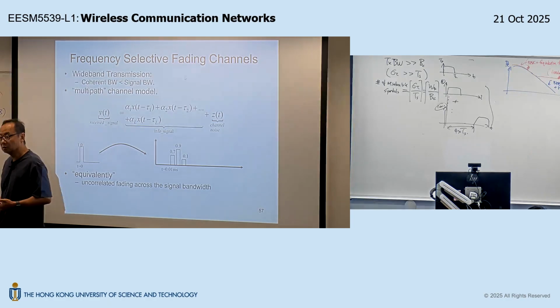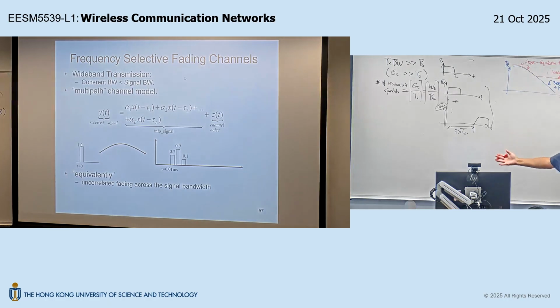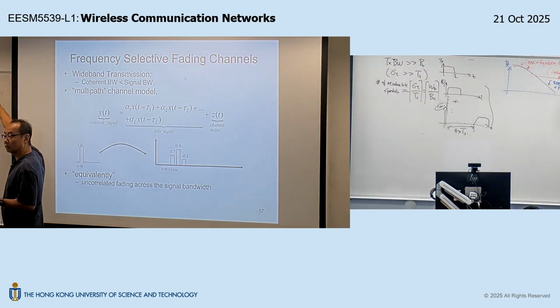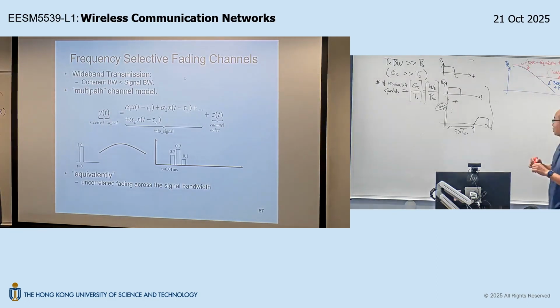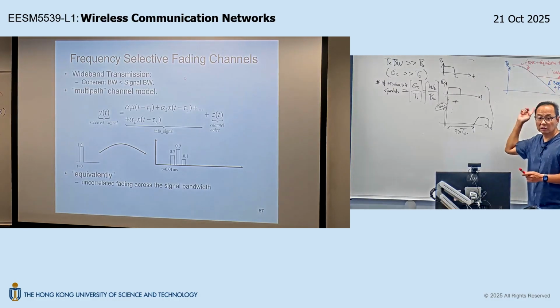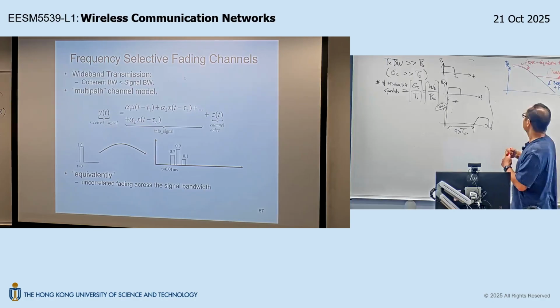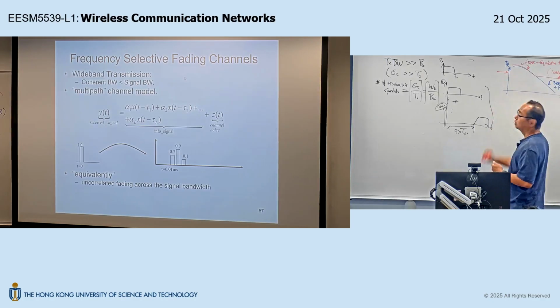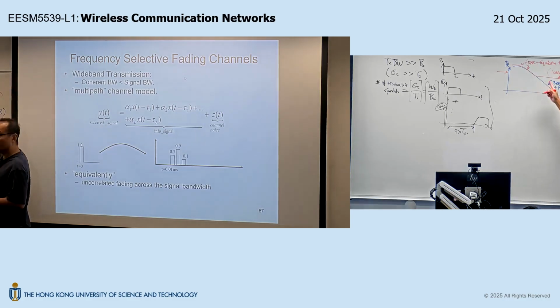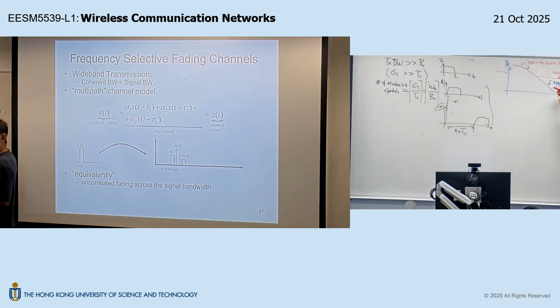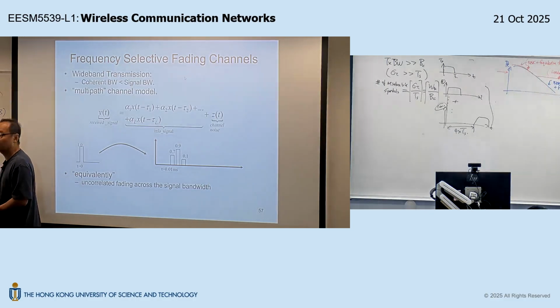So even if you do not mind the extra signal to noise ratio, you won't be able to push the error probability to any level you like. Now, this irreducible error floor may or may not matter, depending on your target error probability. If your target error probability is here, then you do not need to operate in this irreducible error floor region. So the presence of this error floor doesn't affect you at all.